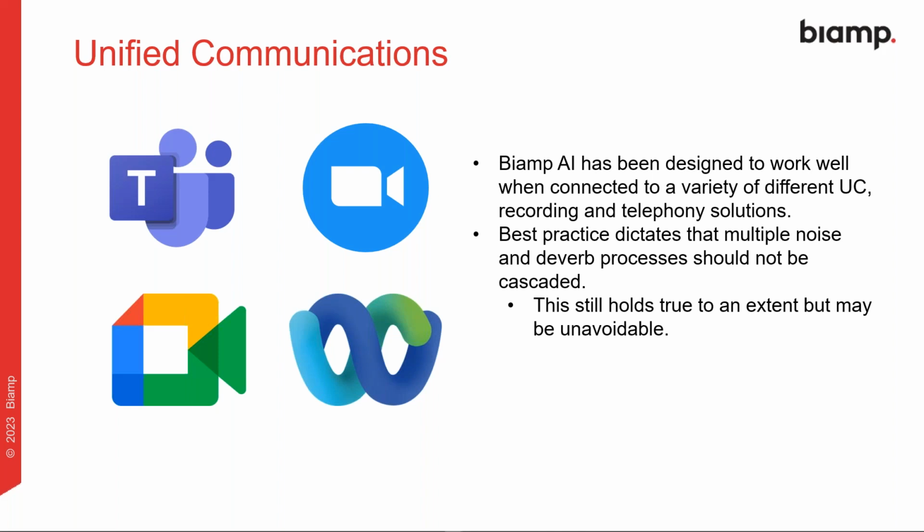The reason being that nowadays the AI processing in certain UC vendors, some of them are very good and they're also very useful. In some tests in particular rooms, I found the best sound was actually using maybe medium noise reduction in the Tesira and allowing the UC system to do its own processing. If you deliver a good signal to the UC system, it's got much less junk that it needs to act on, so its processing is working much less hard. I know a lot of it is cloud-based now, and if you deliver a good signal, generally you're getting a good signal out.